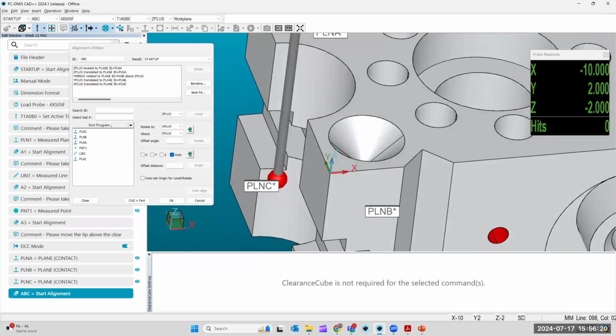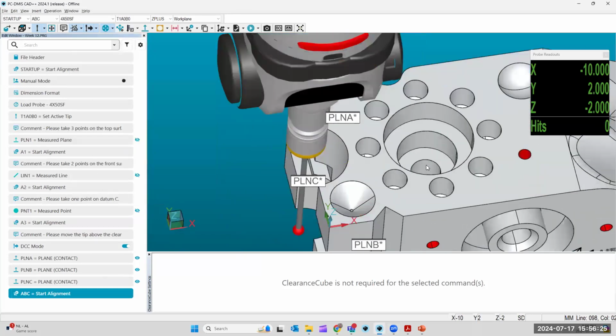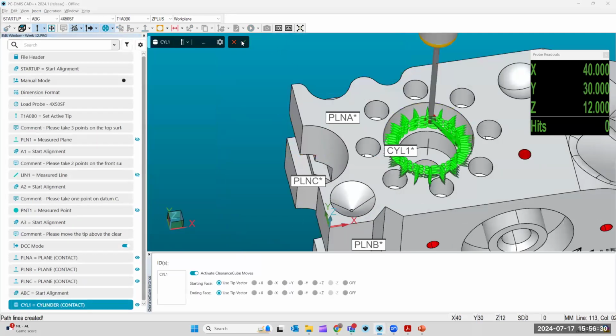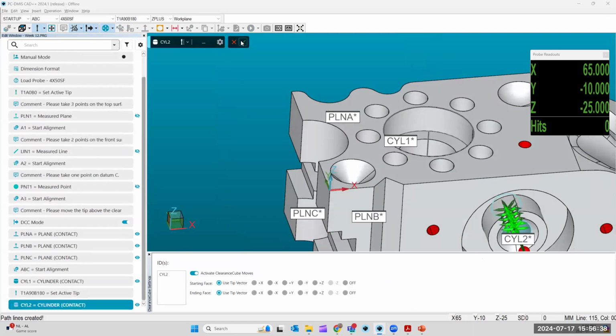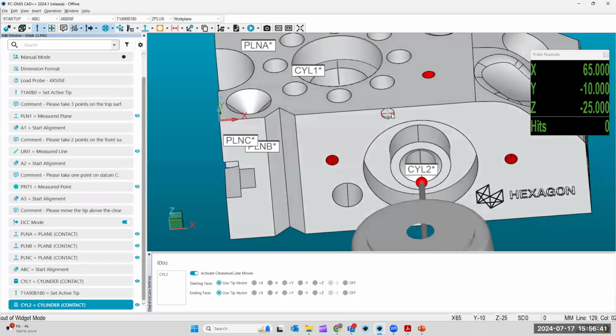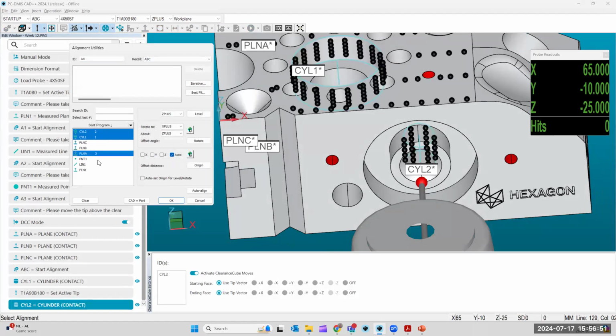What if they were over constrained? If you tried to over constrain something, I will show an example of that really quickly. Here's my D. I'm not going to label these. Here's my F. And so if I asked you to do a DFA alignment, it would look something like this. It would be D, which was cylinder 1, F was cylinder 2, and A is tertiary. So this is theoretically an alignment that you could be asked to do.